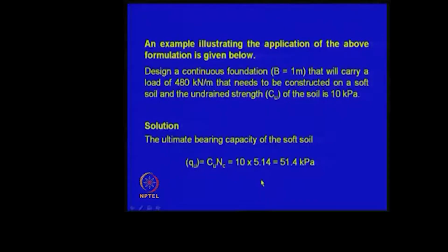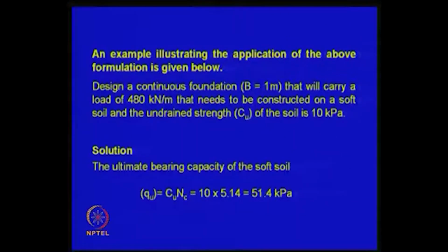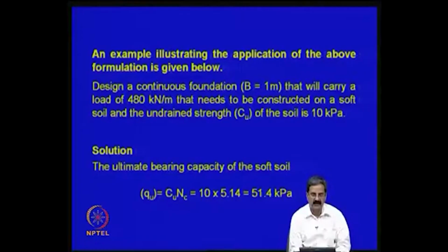I would like to take up a simple problem here, similar to the case that I discussed. You have sand in one case, but you also have clay nearby, but the load is the same. How do you do that? The bearing capacity improvement we need is 480. We have to see whether it can come. The underlying shear strength of the soil is 10 kPa. So, essentially, what I would like to say is that we can solve this type of problem using the